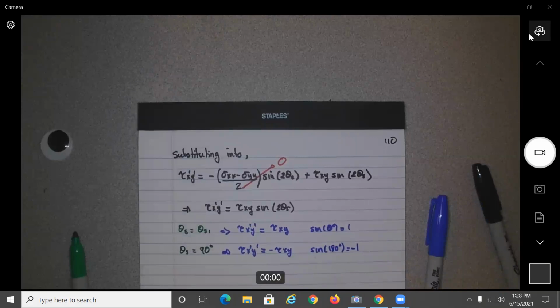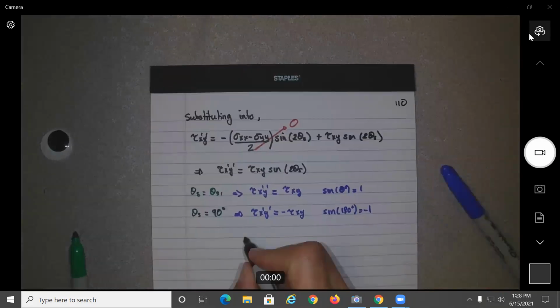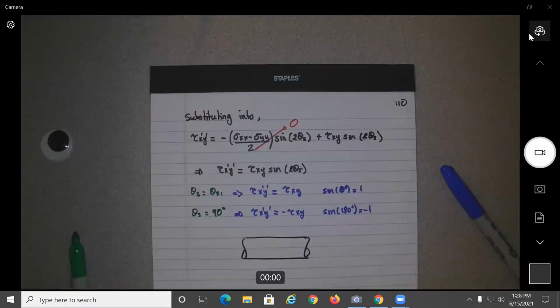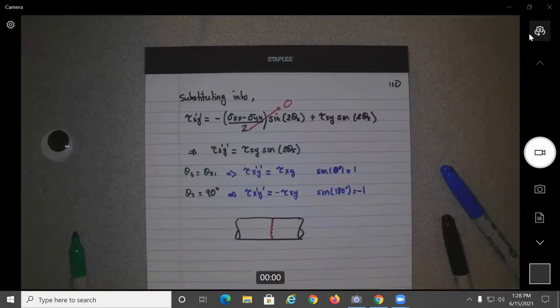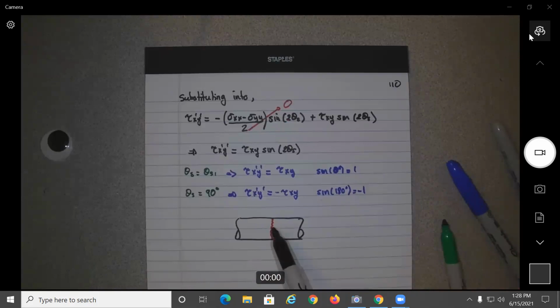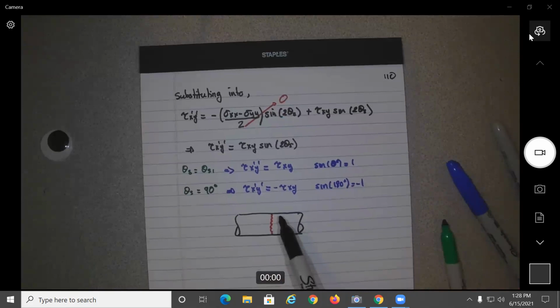All right, so why is this important? Again, now if we observe that our shaft, let's say we are subject to a pure torque and it breaks along this way, what would that mean? It means that the failure is due to the shear, no? Yeah? Okay, so if it fails at 90 degrees or 180, which is basically the same, or here would be straight perpendicular, it will mean that it is due to the shear.